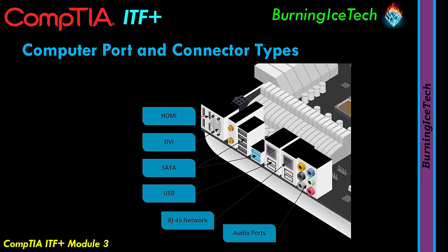Now, normally if it's a black port, it'll either be 1.1 or 2.0. Nowadays, it'll probably just be 2.0. You don't really get 1.1. Those are kind of extinct. So 2.0, that's roughly 480 megabits per second at which it will transfer. If it's a blue port, we consider that USB 3. Nowadays, you also get USB 3.1 and so on and so forth. Much, much faster, but the way you identify these is because it's blue inside. The same with the USB 3 devices. Normally, not always, it'll be blue inside the USB connector itself.